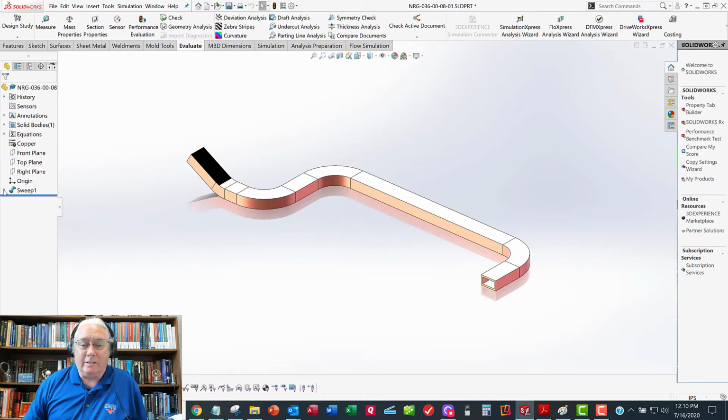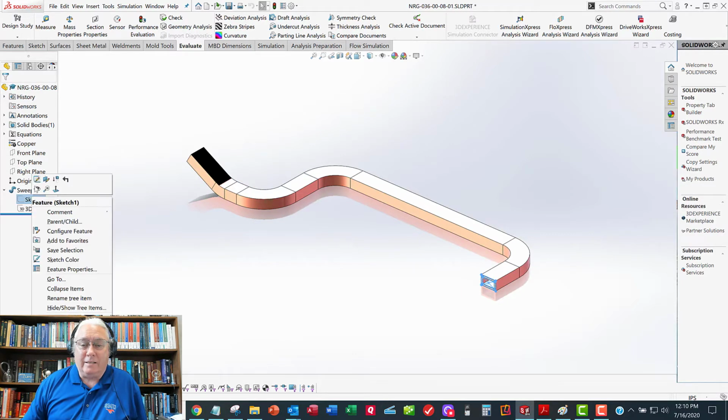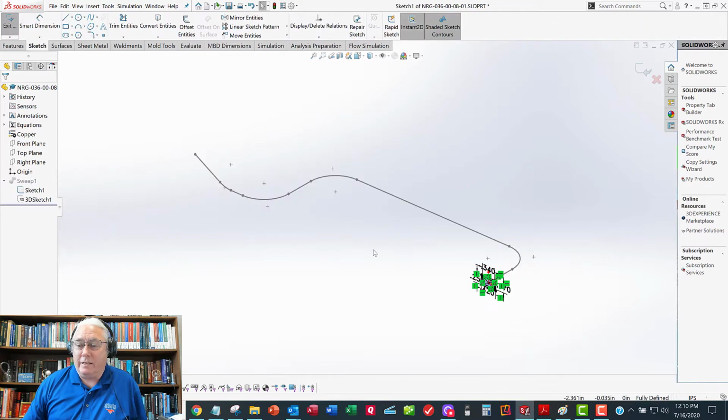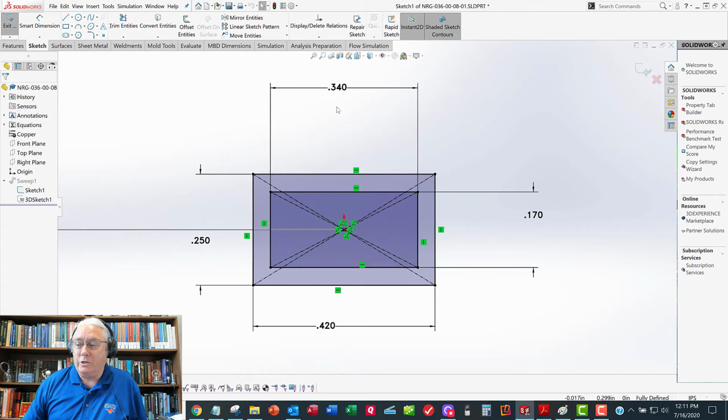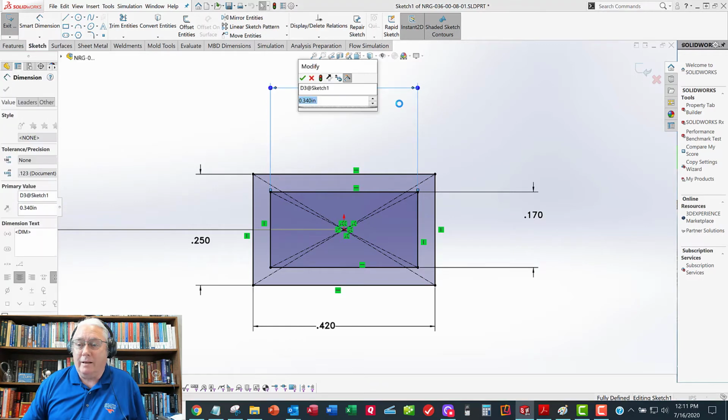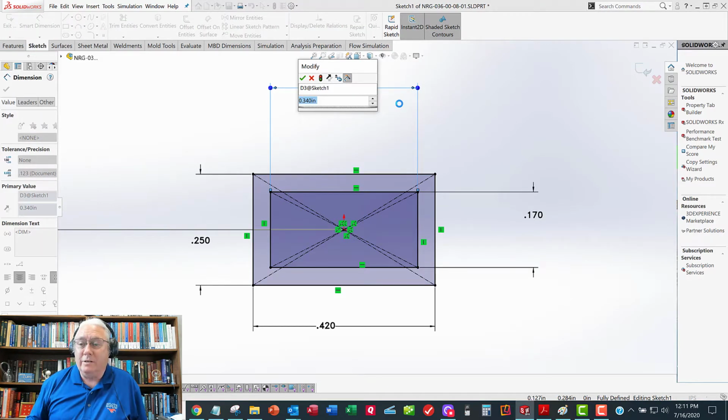And so now the second step is to edit this sketch that contains those parameters, and we're going to change these. I'm going to start with A here, double click, and I'm going to say equals. And it's going to give me this pop-up global variable, and I want to arrow over and choose A as my global variable.